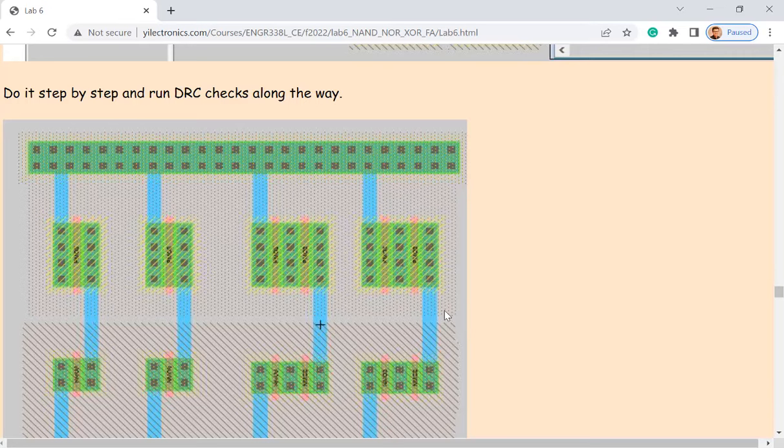And now you'll see the benefit of putting all the PMOS on the top. Right? So you can directly draw a huge rectangle or a box and cover all the PMOSes and put them in the same well. Make sense? So it's just better organized. So the PMOS on the top, you just cover everything, including all the body contacts. Just put everything in the same diffusion.